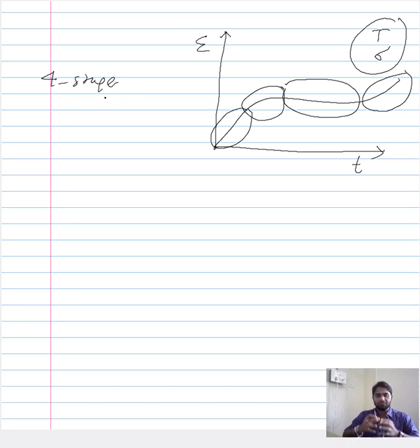That means that instead of the instantaneous and transient creep occupying a single stage, the transient assumes a stage of its own, and the instantaneous creep also assumes a stage of its own. So stage 1 would be instantaneous, stage 2 will be transient, stage 3 will be steady state, and stage 4 will be accelerating creep. These are the 4 stages into which we can categorize the creep curve.